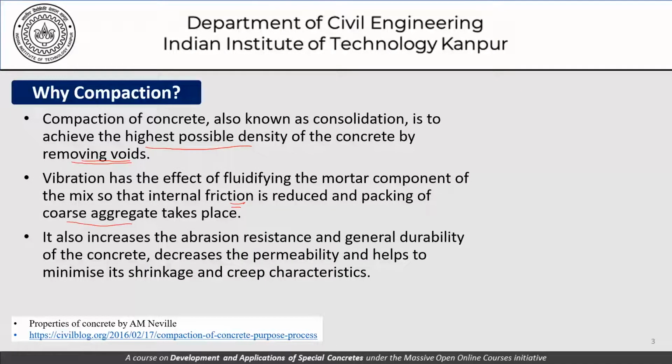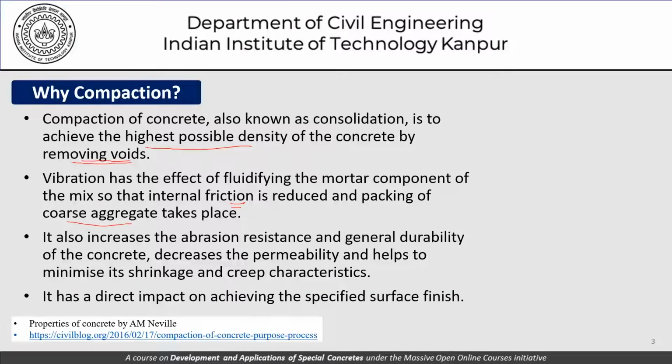It also increases the abrasion resistance and general durability of the concrete and decreases the permeability and helps minimize problems relating to shrinkage and creep of concrete. Proper compaction also has a direct impact on achieving the specified surface finish as far as concrete is concerned.